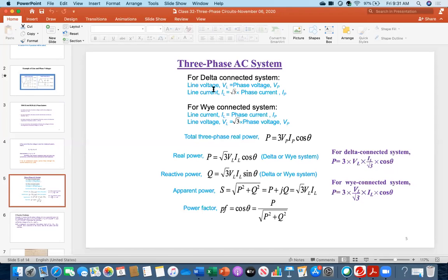Because you see, voltage cannot be with only one line. For voltage, you need two points, either line to line, I mean one phase to another phase, or phase to ground, phase to neutral. So when I'm saying line voltage, this does not mean only one phase. Because if you have a voltmeter, you must connect it between two points. Therefore, everybody keep in mind, line voltage means line to line voltage, simply VL, equal to phase voltage, VP.